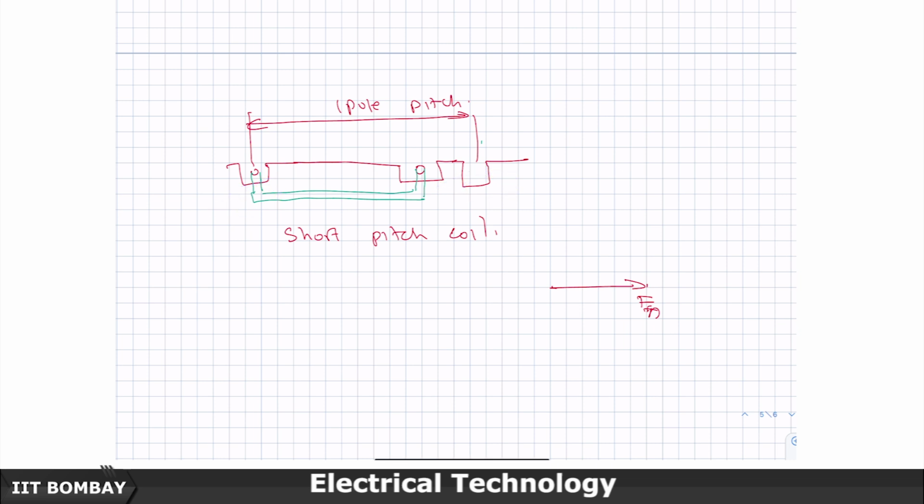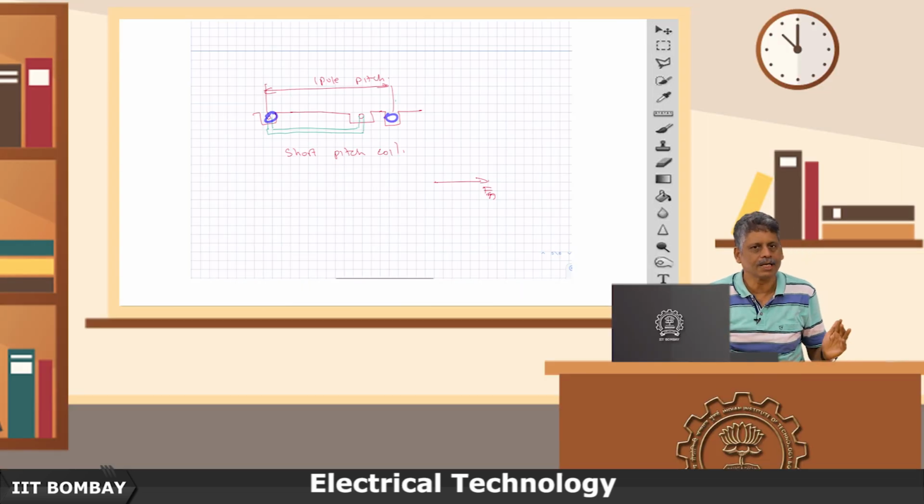The way I did the series connection of the winding, they were exactly in phase when they were one pole pitch apart, and you doubled it basically. So, when pole pitch apart, these EMFs were in phase and I could just add them together.